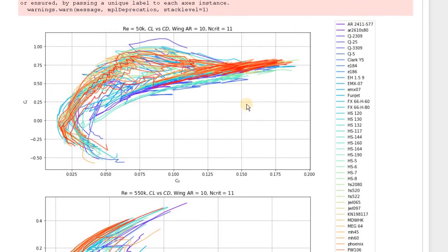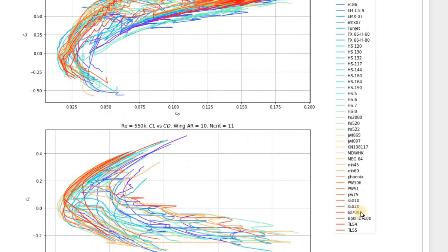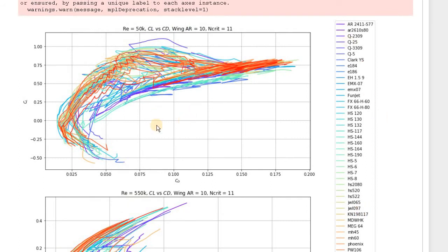In my previous video I talked about this a bit, and what this code does is scan different types of airfoils. So here is the list of tailless airfoils, or flying wing airfoils, and we're going to plot the polar curves. The first requirement is to have the maximum lift at a small Reynolds number, so that we're going to have the smallest possible speed for this airfoil, the small stall speed.